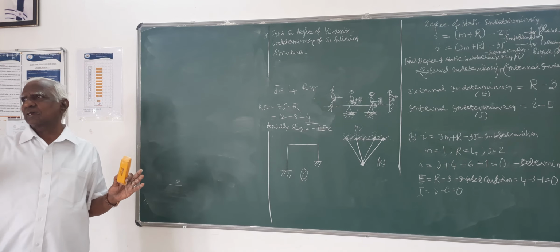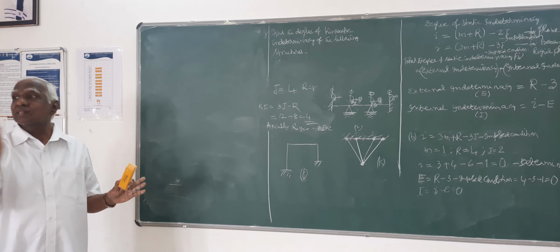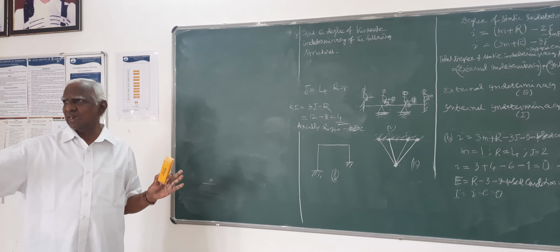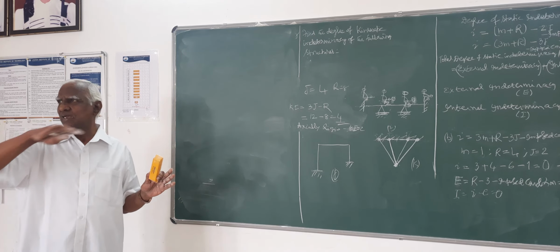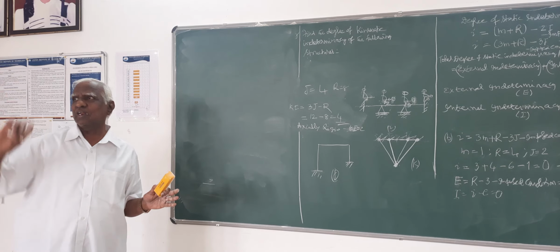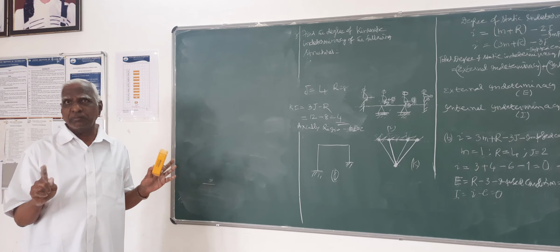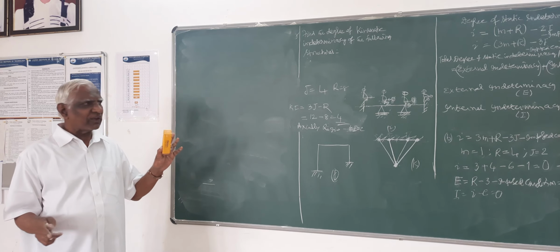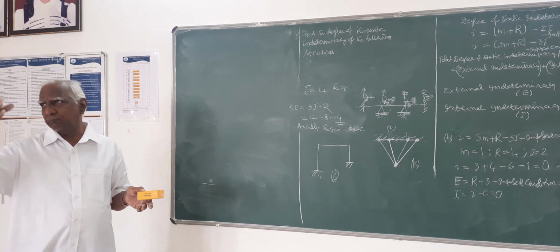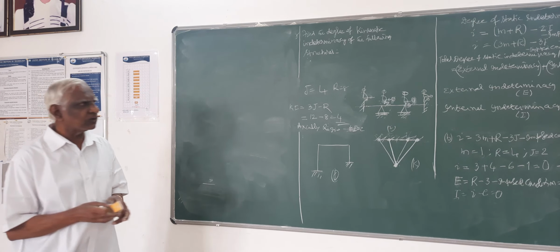At each story level, the same sway will be there: first story, one sway, second story, another, third, another. That point should be very well remembered because it is used in earthquake analysis also at each story level, only for column members.